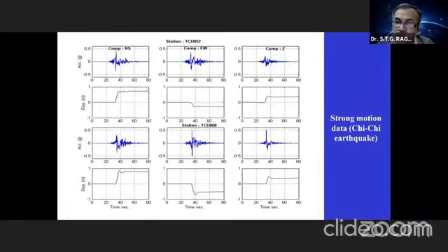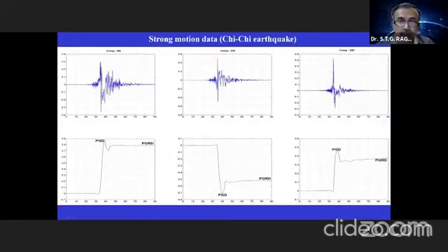It goes to some permanent displacement, you follow, right. This effect I showed you in my starting slides, the permanent ground residual displacement, or we call this a fling in seismological terms. You can see for the Chichi earthquake, the fling was almost 1 meter, and it is almost the same as the peak ground displacement itself. Now this is for another station, TCU 68. Here also you can see this fling. I'm just zooming the previous figure, so you can see this is what we call PGD, and this is PGRD.